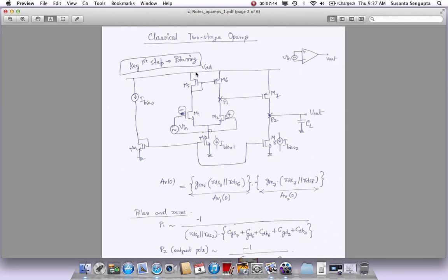This is a gain stage. Okay, it has a differential amplifier as the inputs with a current source, a tail current source, and it has got a PMOS current mirror load. So from this differential input to this point output, we have the gain, and the gain is pretty high depending on gm times rds, and we'll go through it again a little bit. So this provides the first gain from input to an intermediate output. This is not the final output of the op amp.